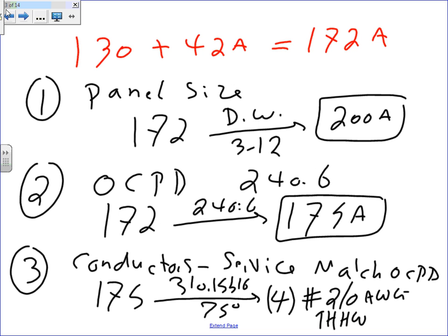I'm sorry. I came up with 2.5. 2 inches, 91% full. I wonder why. This calculator came up with 2 out, right? Clear, clear, clear. 2.5. A lot more room, but 2 will fit. 4 conductors, THHW. Did you use THHW? Yeah. And conduit size 2. No, 2, you're right.